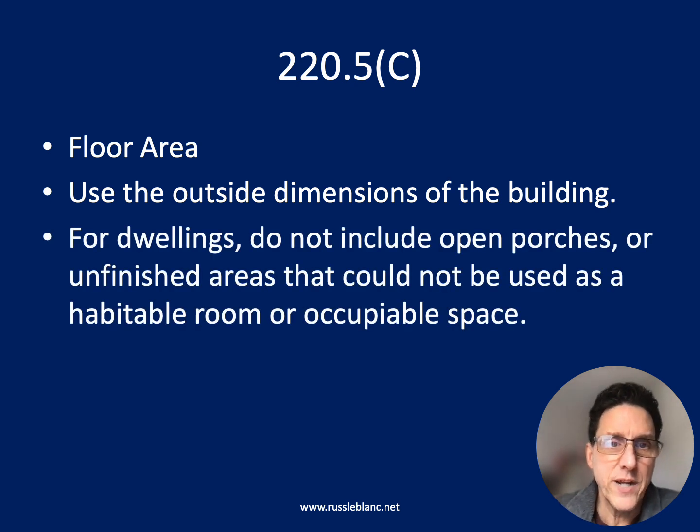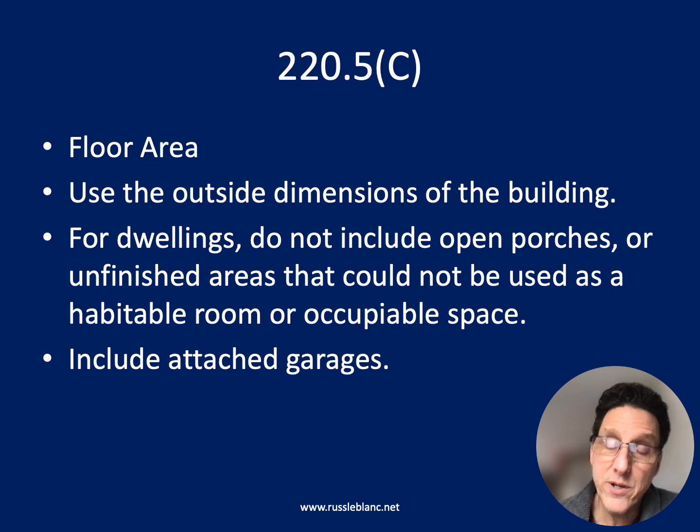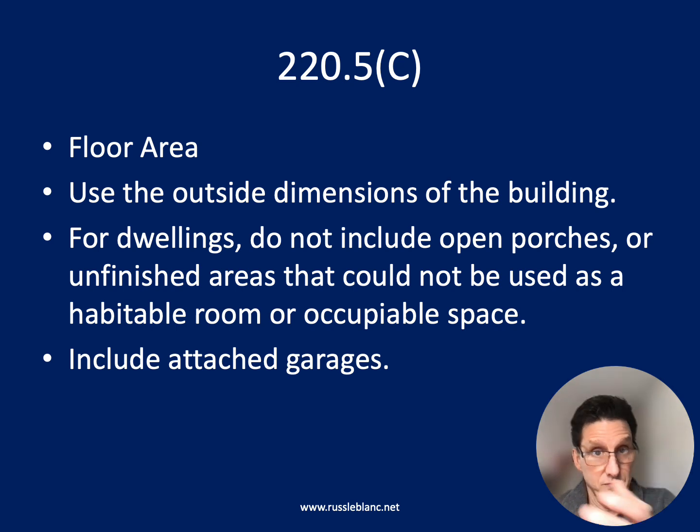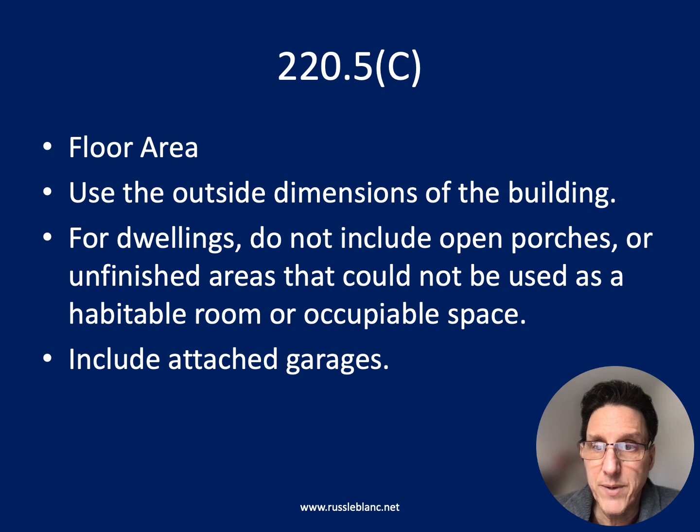So don't include any of those spaces like open porches or unfinished areas that wouldn't be used as a habitable room or occupiable space. I would include the attached garage now. It doesn't specifically say to do that, but knowing that they removed it from being excluded, I think the intent is to include it now in the area.